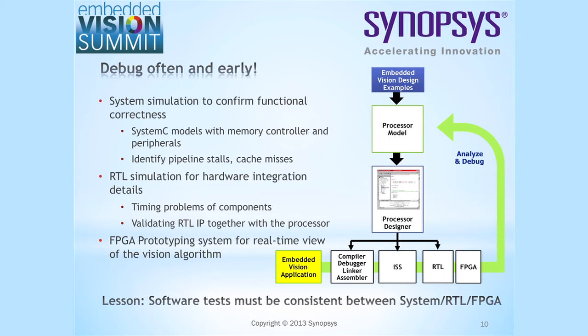And in the FPGA prototyping, hopefully you will only be debugging the difference to the logic level, which is configuration of components. And for that, to prove that this refinement can be done, you need to have lots of software tests, not just the algorithm under test, there to show that you have this consistency.